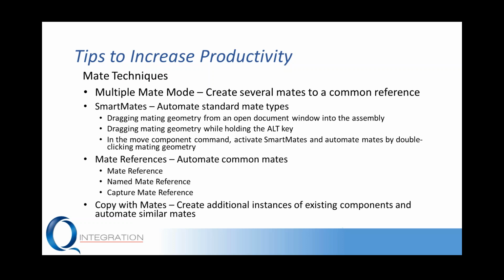So if we've already inserted a component into an assembly and we've created all the mates, and we want to then add those mates as a mate reference to that particular component, we can utilize capture mate reference to do so. And then creating additional instances of components in our assembly.